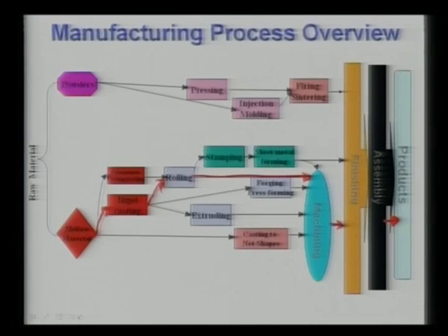There is another way of making the same plate, the continuous casting or continuous rolling route. Continuous casting means the molten metal is poured into a mold and continuously cast through the continuous caster machine. Then, depending on the thickness of the rolled product that you want, this continuous cast product can be subsequently rolled to the desired thickness, and then go to the finishing and assembly stage.